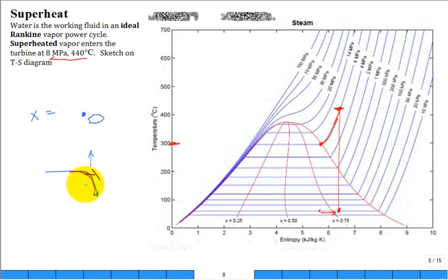Cavitation, right? So instead of having gas pockets that then quickly collapse, here you have water that impacts the solid and then does essentially the same type of damage. So high quality steam, we need it out in this vicinity if we're going to exit. So what we'll do is not just superheat, that helps, but we're going to stop and expand it to 2 stages of turbines.